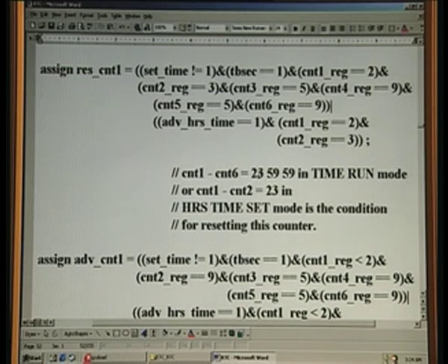So what is happening when you want to set, after 23, what do you expect? It should become 0, 0, right. But we are concerned with only counter 1. So, as far as counter 1 is concerned, after 23 you do not bother about 59, that is only in the run time, whereas now we are bothered about setting the hours display alone. For hours you do not have to bother about minutes and seconds, that is why we are stopping right here. So, this statement stops with just 2 counters, because we are vitally interested only in the setting of the 2-digit hours.